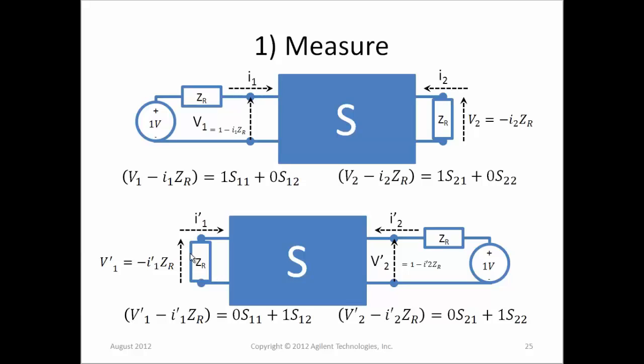And I put a reference impedance on port number 1, and that forces my prefactors here to be 0. So I can trivially determine now my S12 and S22 in this situation. So with two setups, two measurements in each setup, I can determine the 4 equations, the 4 unknowns. I know all my S parameters.